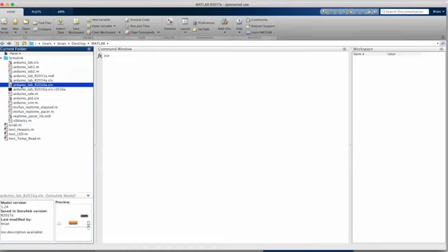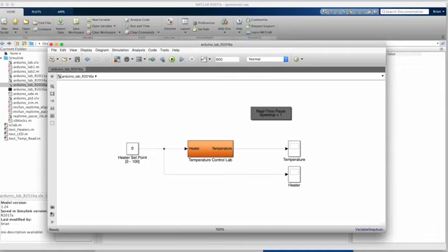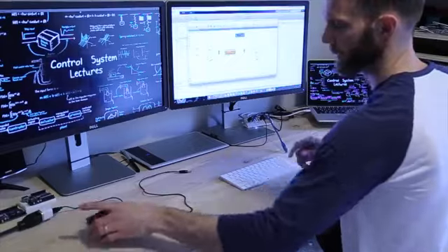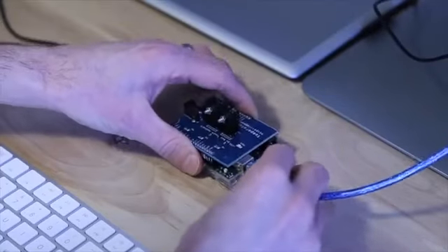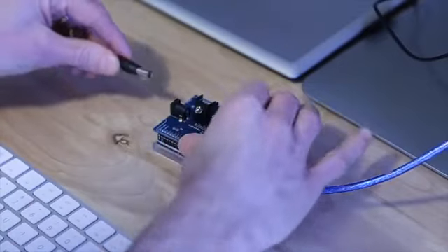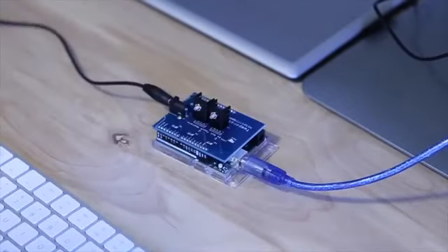I'll open the Simulink file and show a very basic system. The orange block is the software that communicates with the test hardware. You can think of this block as the physical hardware sitting on my desk. If I send a heater command to it, it will physically turn on the heater. Now I can set the heater between 0 and 100% and get the resulting temperature back from the hardware. This gray box ensures that when I run this test, it will run at real-time speed. And at this point, I just need to hook up the hardware to my computer so it can talk over a serial bus, and also to a power supply to run the heater. And now, we're in business.